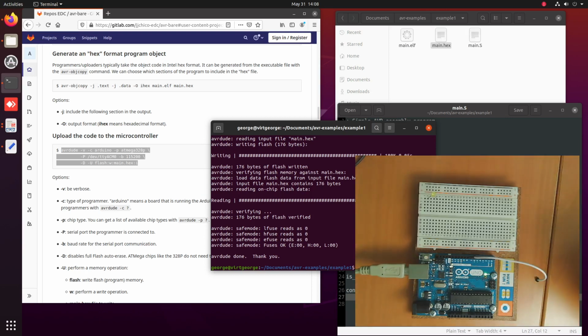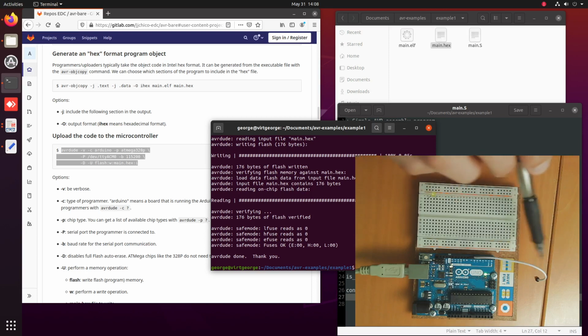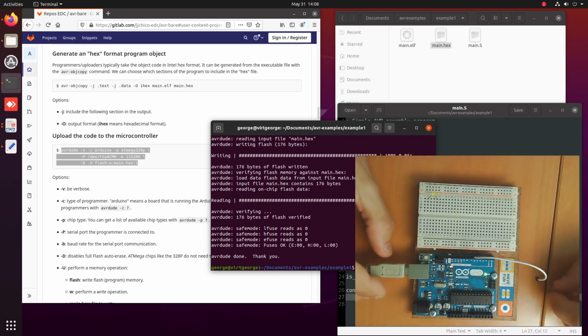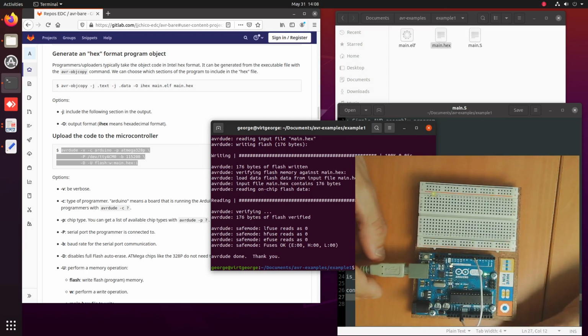Because here it's in high impedance, it's left to the air, so depending on the electrostatic charge, it can change from one value to another. So we have to connect it to 0 or 5 all the time to avoid wrong behavior.